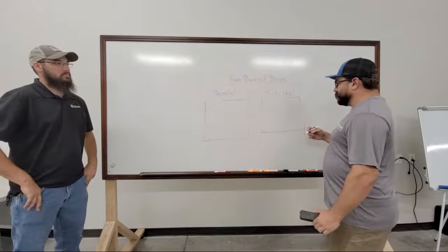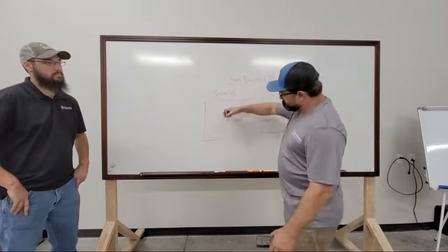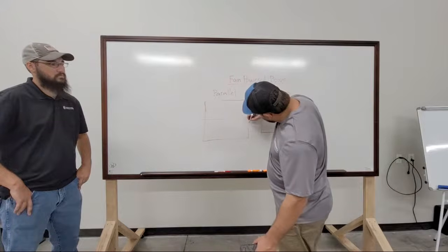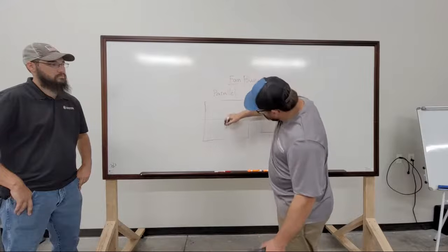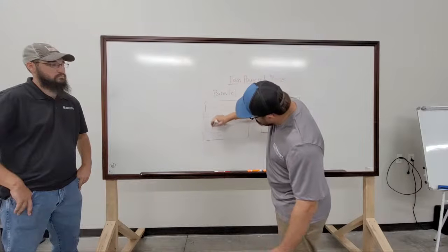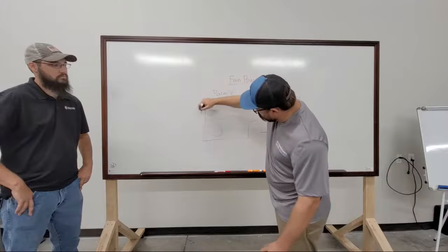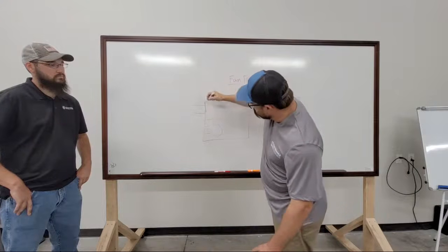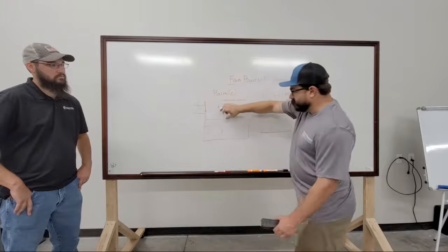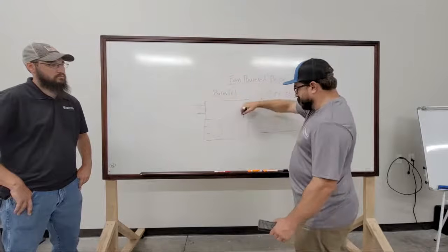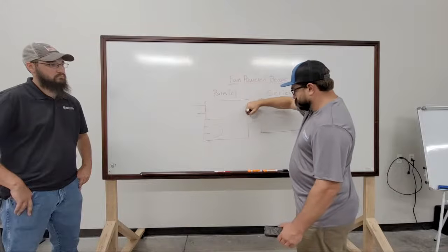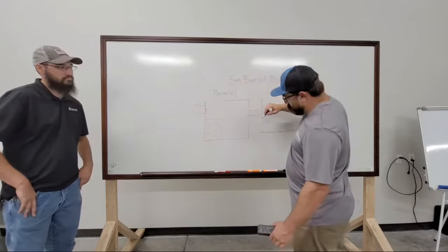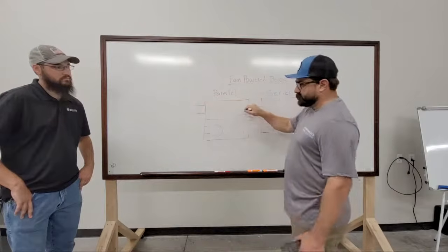In a parallel box, you have a split cabinet and a single outlet. You'll have a fan that draws from the return plenum and a damper that feeds your supply air. Inside of the cabinet, they mix together and they push out through the outlet. Either one can supply the pressure.